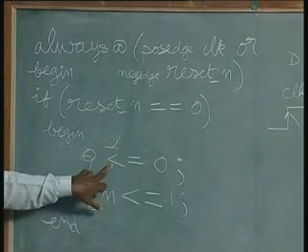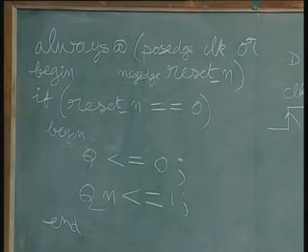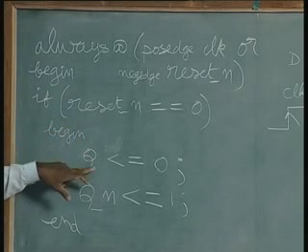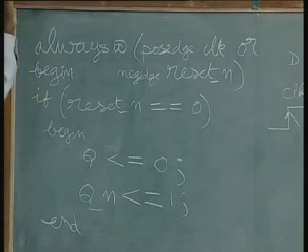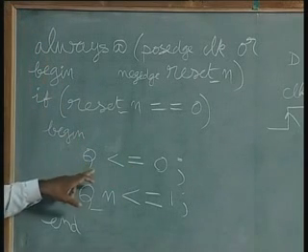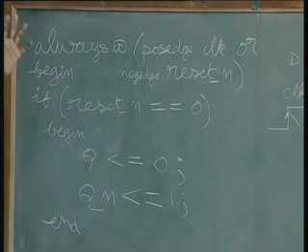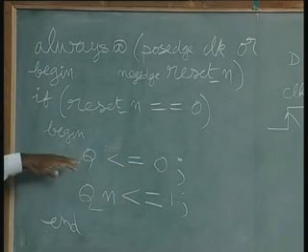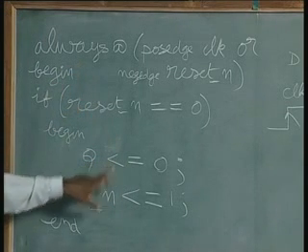It is not less. You have to read this together. So this distinguishes assign statements from this. In assign you used plain equal to, all combinational you use that, and here you have to use what is called a non-blocking statement. The earlier one is called a blocking statement. If you don't put this one, again the tool will complain. So take care of this.